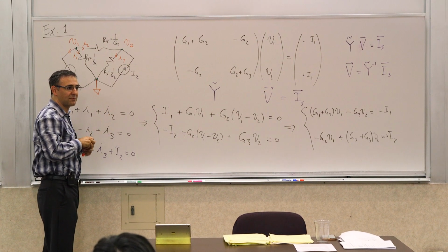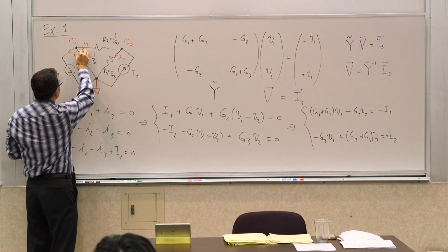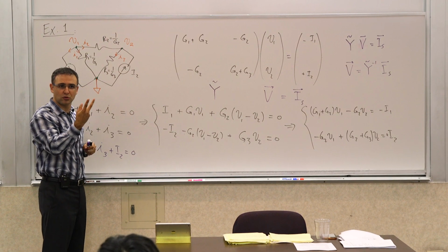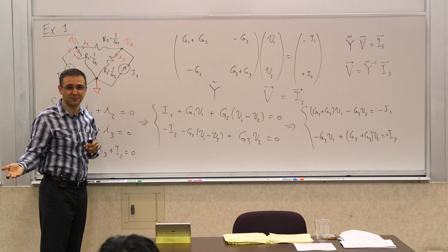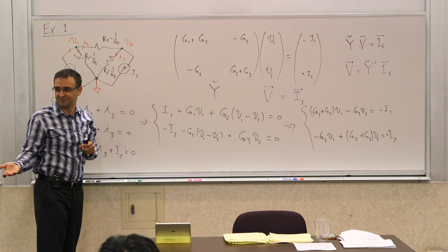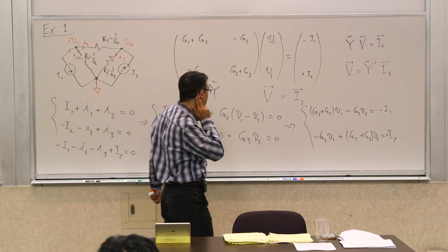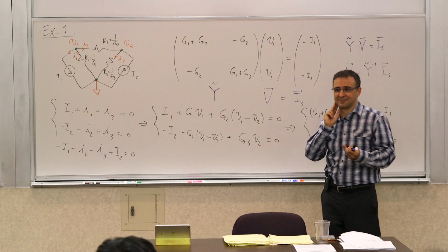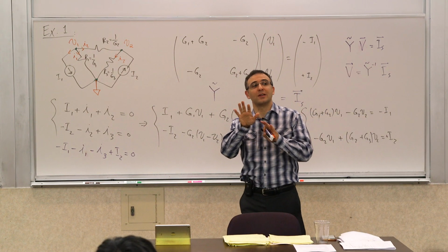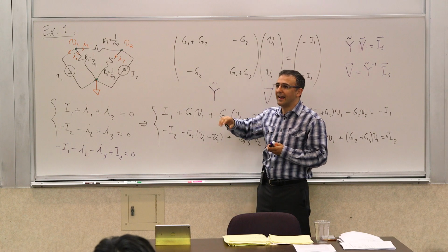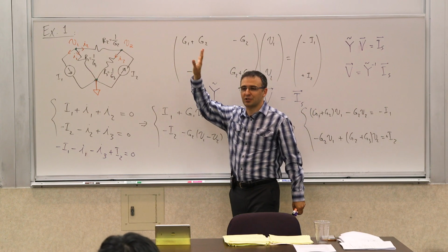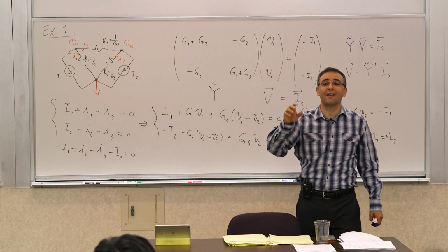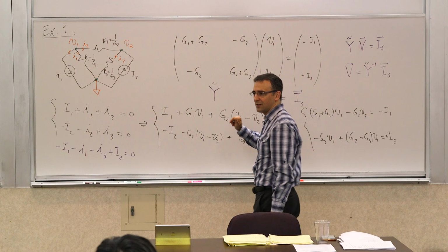Anything else? The same thing, you want to say the same thing? Sorry. Yeah, so the hypothesis is that it's basically the conductances attached to that node directly. And those two rules seem to produce, at least in this example, the correct answer, right? So those two rules are, in fact, correct, with some caveats. We'll talk about that. I can tell you what the condition is: as long as you don't have dependent current sources in the network.